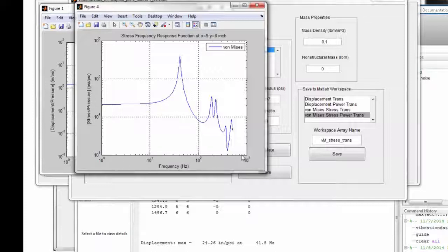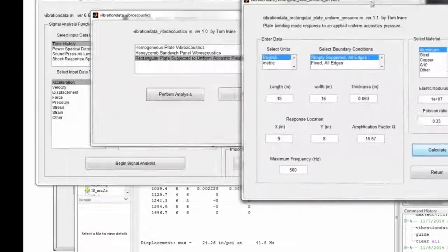Again, this is versus frequency in hertz. Again, we have the fundamental mode at 42 hertz dominating the stress frequency response. But there are some also contributing effects from higher modes as well. So we see the higher mode contributions there as well. So if we just want to do a simplified analysis, we would only include the first mode. We could include additional modes, but we get a diminishing returns effect as we include those. But all things considered, it is a wise choice to include the higher modes as well. So we've taken a look. Oh, we need to take a look at one other thing.